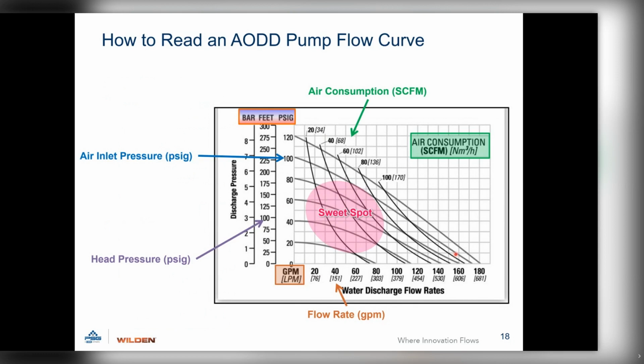Now, sometimes you're already maxed out, you have the biggest size pump there is, and you're still running out here on the far end. Well, that's okay. You can still do that. All it's going to do is wear out some parts faster. So we recommend keeping your sweet spot right around this portion of the curve here.